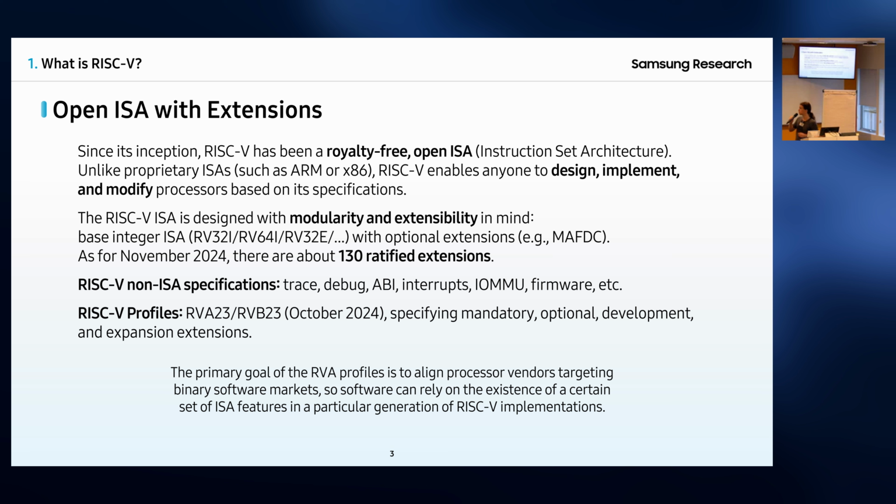And coming to the flexibility, RISC-V is very modular and extensible. It was designed to have a solid integer processing base, where RV stands for RISC-V, 32 bits, and I stands for integer base extension, which is like 40, 50 RISC type instructions.